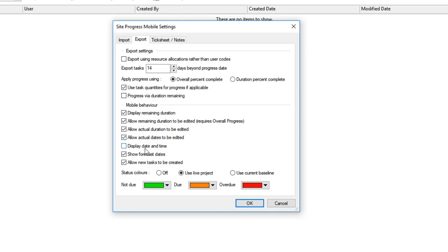If you want to progress activities at a finer level of detail than a day definition, then tick this box, because then you get an hour and minutes selector on actual information, and you can have that information at a greater degree of detail.